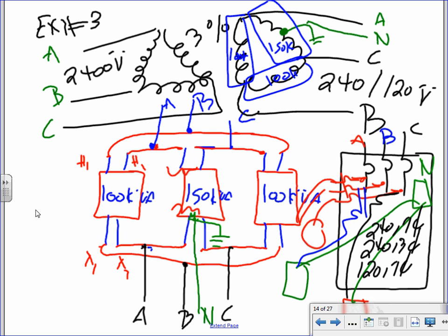They go to the guts of the transformer, pull a wire from 1 transformer, which is that boy here, and that is grounded, and they pull the neutral. So you get phase A, B, C on the secondary with a neutral. On the primary, you get 3-phase. Can I get you guys to understand this is used only to get 240/120 3-phase? With it, there's the wild leg. Remember that B? Where's phase B? Phase B, the wild leg, the voltage between the neutral and B is 208, not to be used. We don't use that voltage.